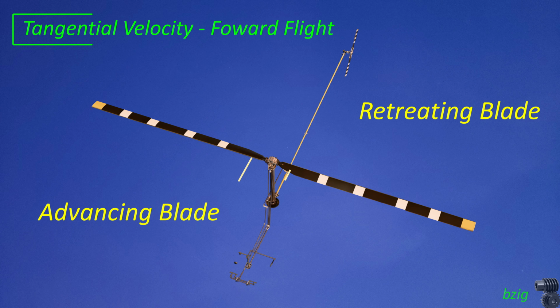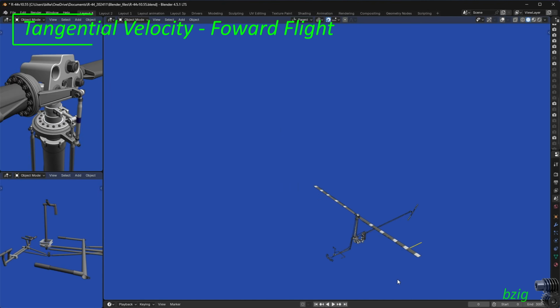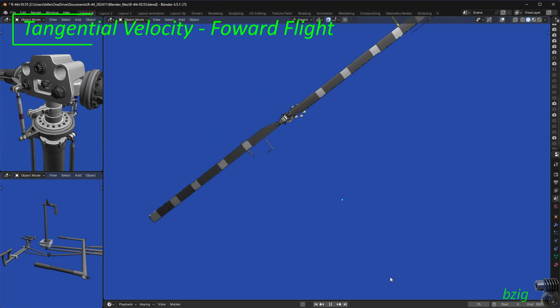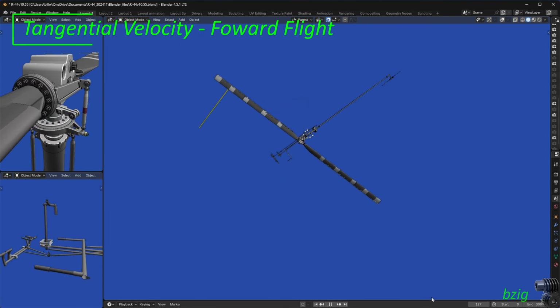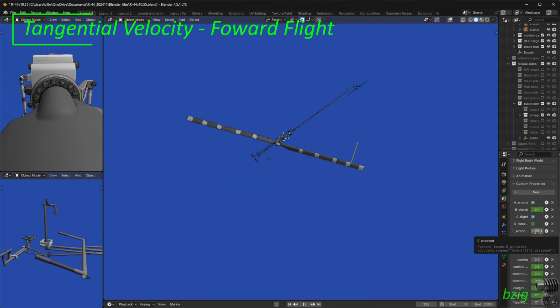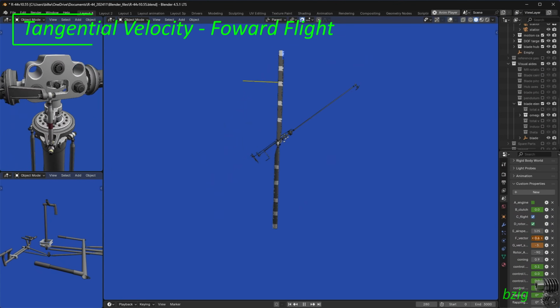And interestingly, when I slide this to the inboard blade section, you can see the part of the retreating blade with this region of reversed flow. I hid the net aerodynamic force vector and the total velocity vector in this forward flight simulation because the only forward flight consideration in the math model is the velocity component. If I were to show these other vectors, they would erroneously show a reduction in lift on the retreating blade.